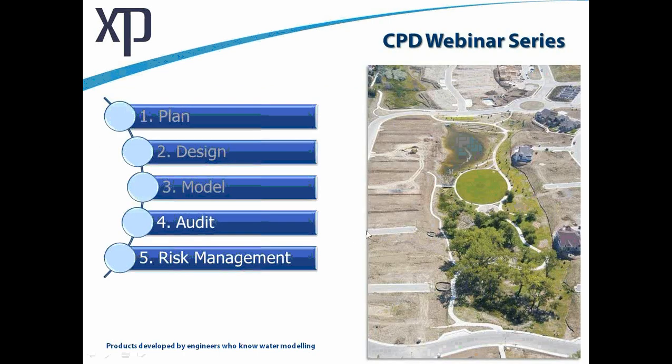I'll just do a couple of slides and then we'll run live with the demo. Just to remind ourselves, we have some new attendees today. We've run through a systematic approach on sustainable drainage design. That started off with planning out where we can put these particular structures, whether they're basins or wetlands, swales, etc. So there's a lot of planning thought required to make the space for the water, to make this a better environment, and to consider the overland flood routes even at the beginning of the design process. This is one of the fundamentals that we need to do.